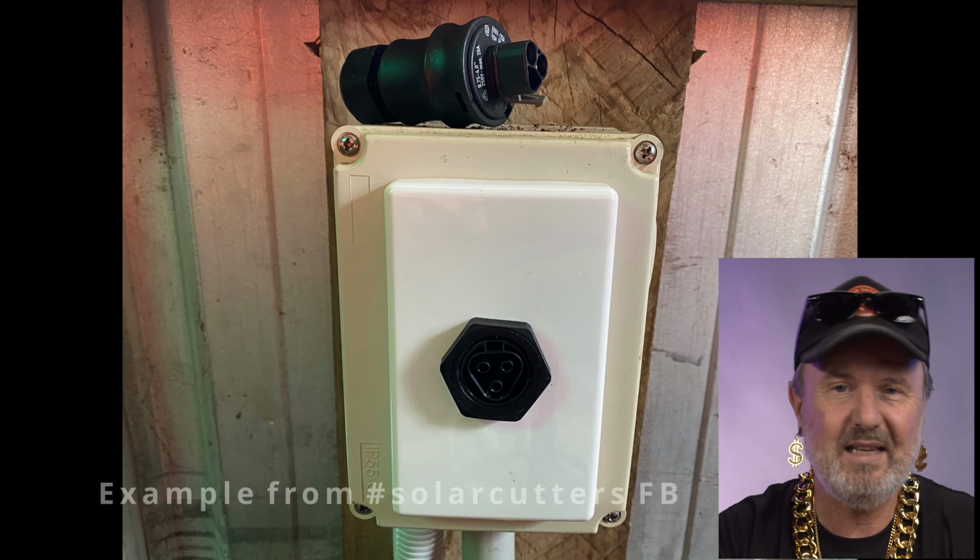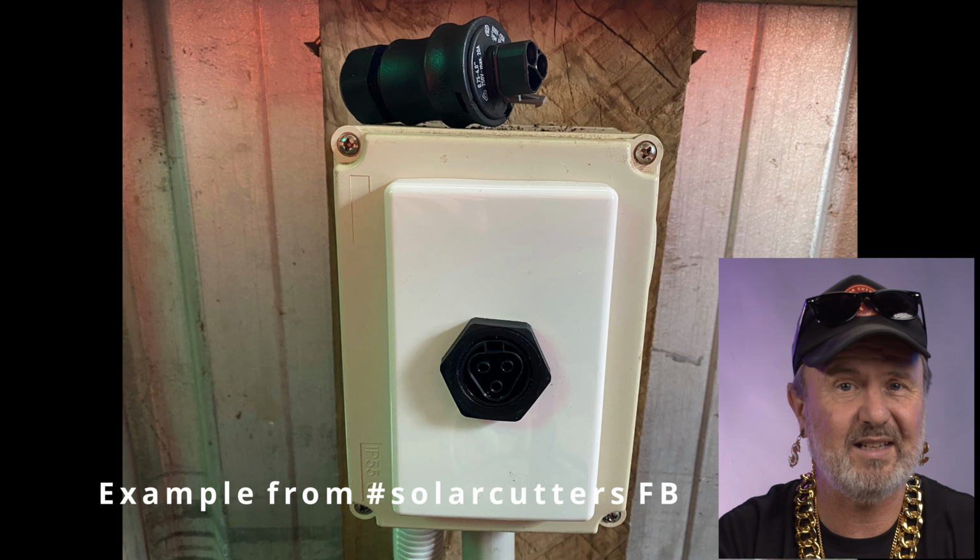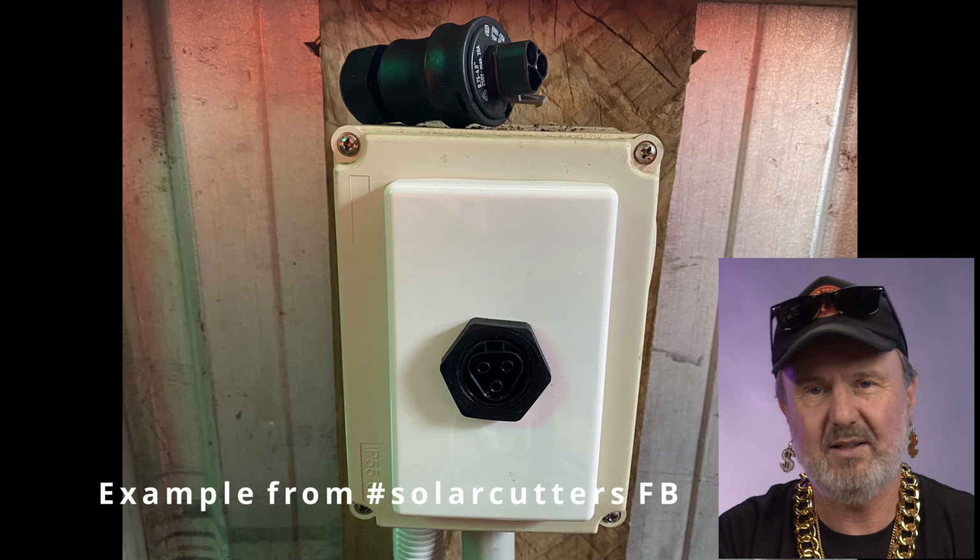It doesn't have pilot pins, but it's got another solution. Many inverters actually have a screened to IP4X AC installation coupler. That means you can plug it in, and it's locking often, which is another bonus, so it can't be accidentally unplugged. The male pins are screened, so there's no live parts that can be touched, and it's regularly used on interactive inverters, grid-connected interactive inverters, interacting with the utility grid.